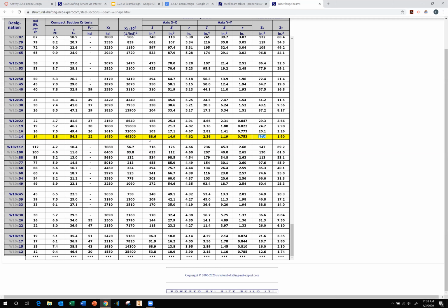It's like, no, don't worry about that yet. They were trying to ask, how do I solve deflection? Do I have to solve for E and I? And I said, no, don't worry about that yet. You're going to learn that the next assignment. The I is right here. It's 88.6, which means that this specific beam, its moment of inertia along the x-axis is 88.6 inches to the fourth power.